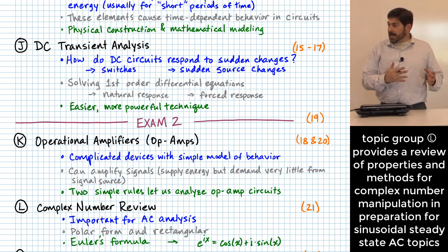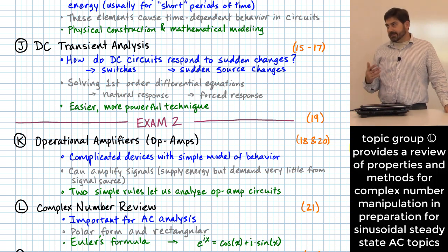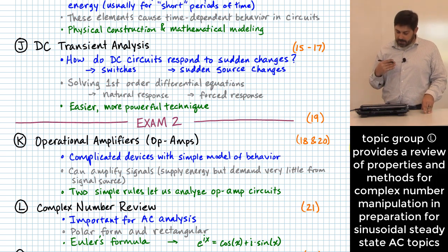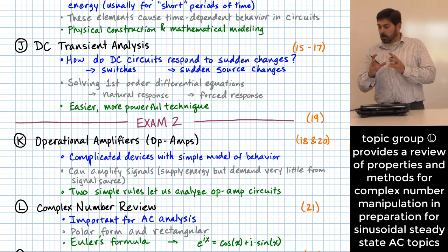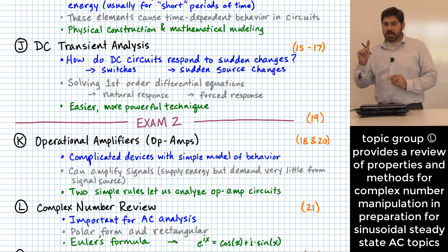When we're analyzing those kinds of circuits that have alternating current, without some kind of tool it would be pretty daunting to figure out what happens in circuits where we've got waves instead of some constant value, okay? The good news is we can use complex numbers to set up our problems in such a way that they are solvable using all the exact same techniques that we used for our DC circuits, but we can do them for AC circuits with one change.